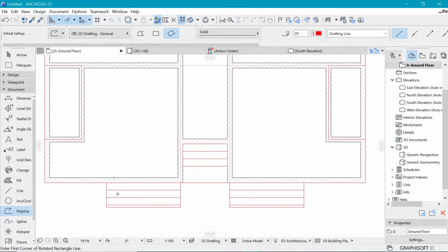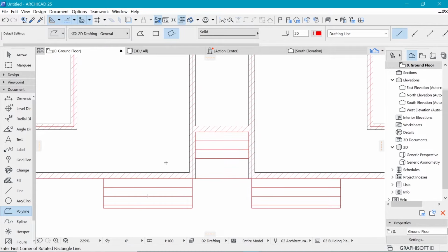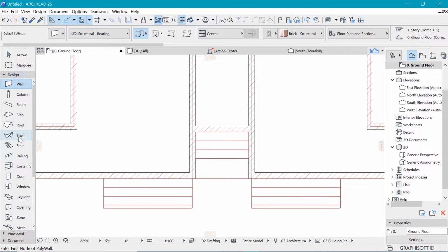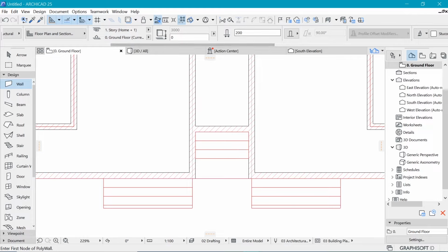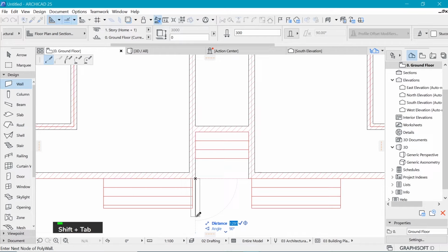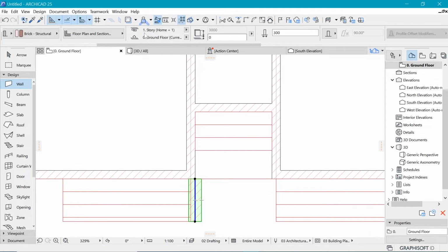But finally, let's just put some walls on this other side, which are nice features to have, and these walls are going to be much thicker than the ones we have. So let's select this wall tool here, and we need to make them 300 millimeters thick. So if I scroll here, I can see that wall thickness and make that 300, and then I go ahead and draw that 300. But remember, we chose something like 1 meter. Yes, there.